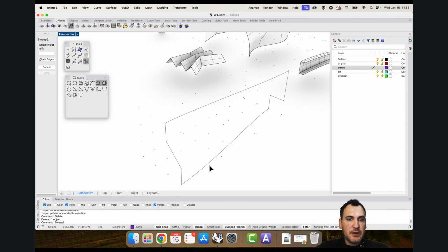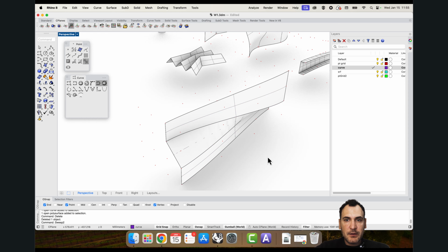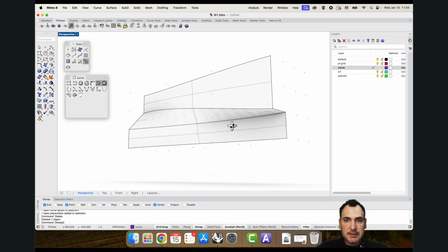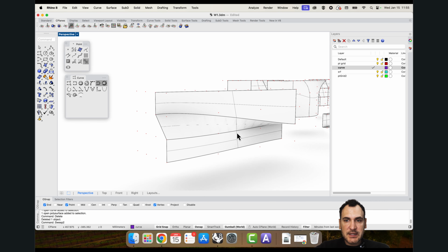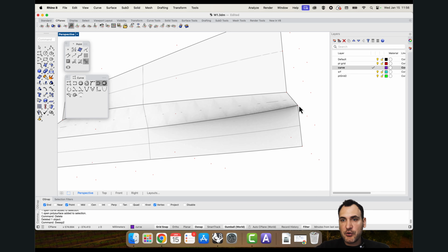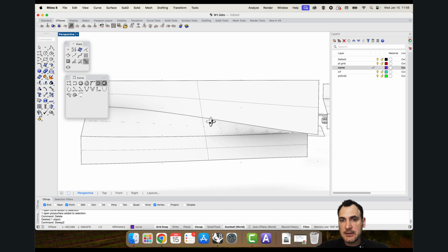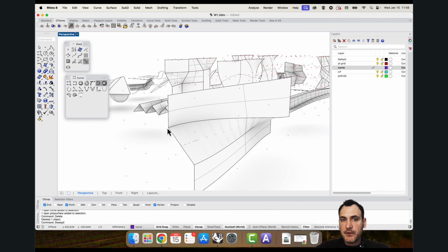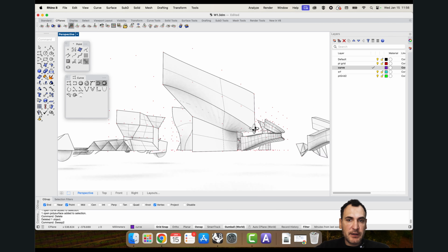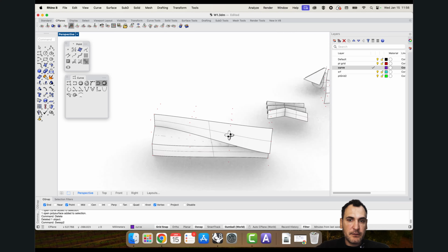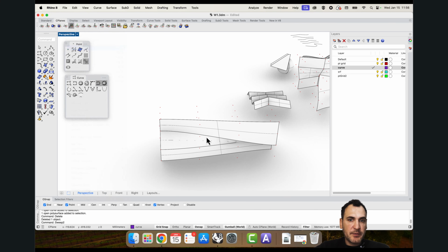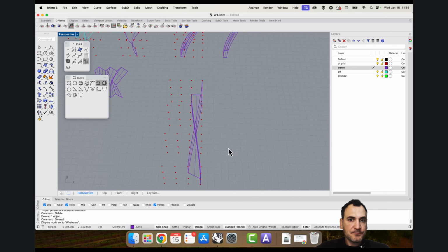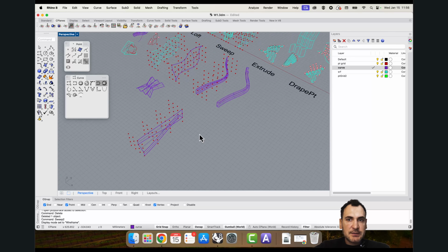So we are defining the boundary of the surface. So it gave me something like this. So you can see all these edges are twisting and merging onto these other profiles. So Rhino does a good job of finding this correlation between the profiles, and you can get very nice geometry modeling like this. So that's essentially sweep 2.